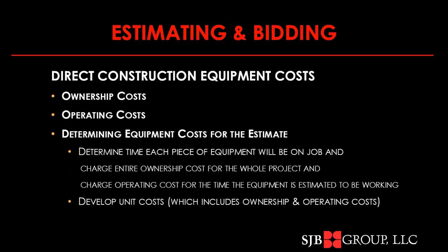And then in your takeoff, you need to track the use time for that equipment so that you can charge the operating costs correctly. So you're going to charge operating costs only when the equipment's used, but you're going to charge ownership costs whether you're using the equipment or not, as long as it's on the project.